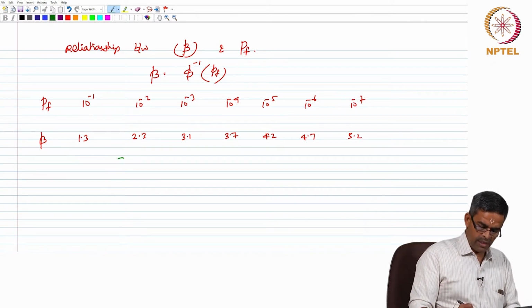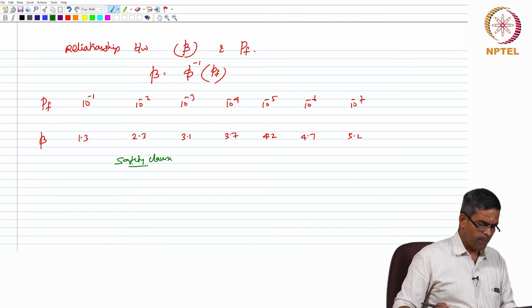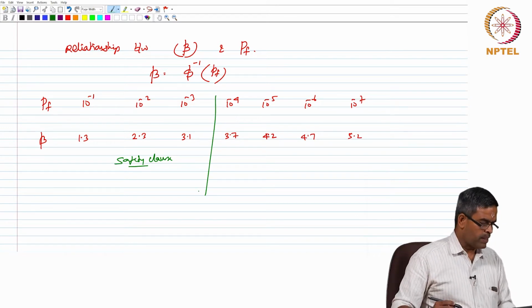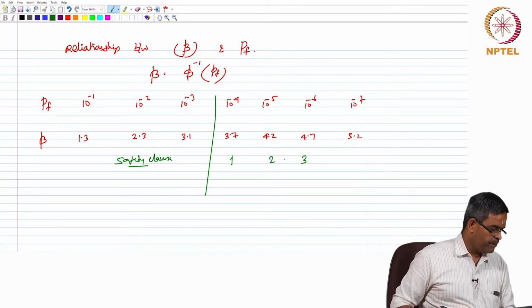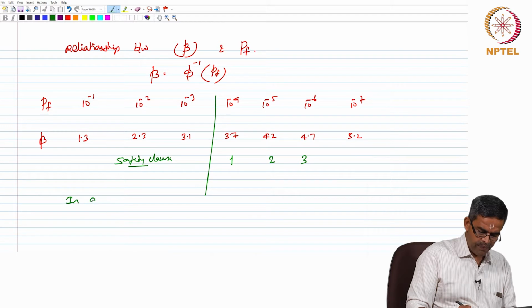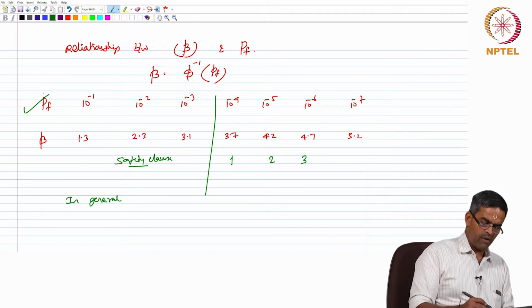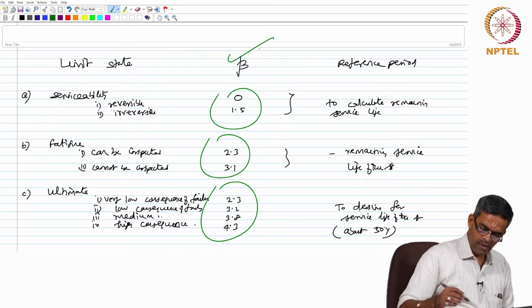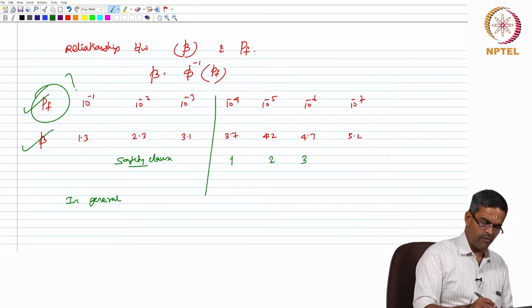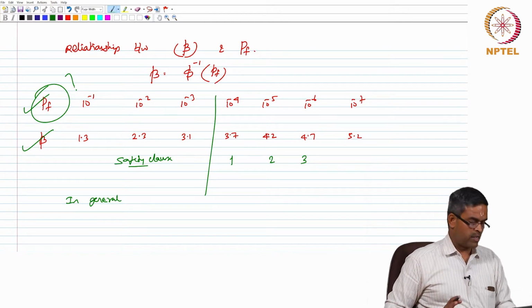However, friends, interestingly there is a safety class which is also introduced depending upon the reliability index. So, this safety class is 1, 2 and 3. In general, if I know the probability of failure, I can find the index, or if I know the reliability index, I can always check what my probability of failure of a given system is, which tells me the assessment of the structure, which is actually accumulated and collected from the continuous monitoring data.